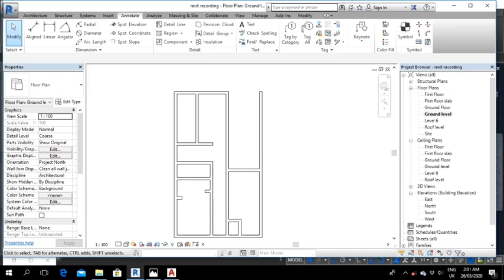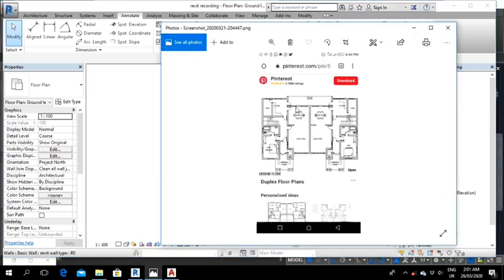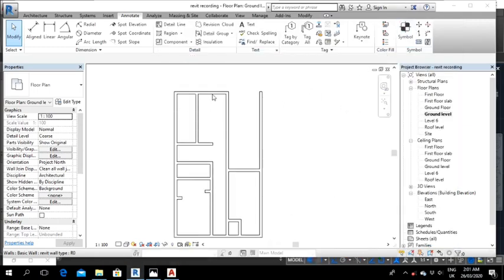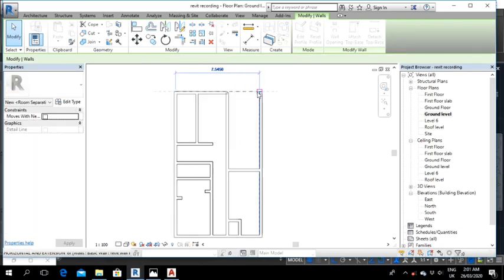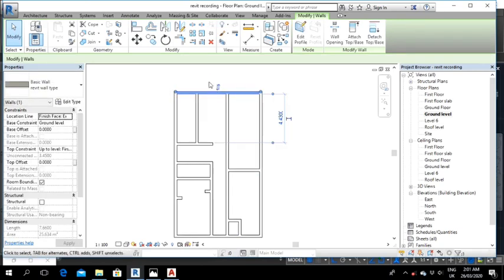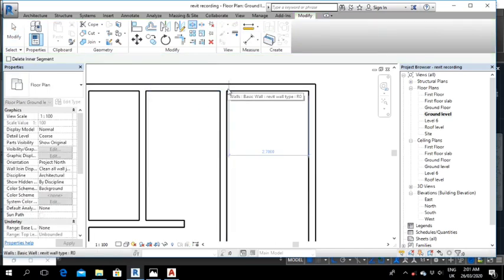The next wall in our design is this wall here. Okay, that's this one exactly with the passage. Okay, so I know the distance between this wall and this one is 1.2 meters. So let's represent it in our drawing. The first way is just select this and extend it to this end. Then the next thing you're going to do is to split this wall. So click on this, make sure it's at the wall face, and then split.